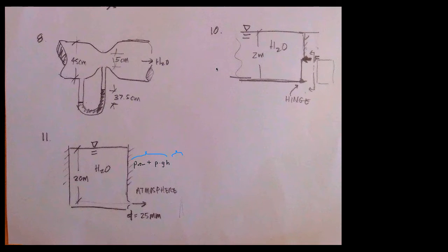But of course you know that this Venturi tube, the way it works is in a steady state condition of flow, the velocity times the area of this section must equal the velocity times the area of this section. So this has a faster velocity. And you know that the higher dynamic velocity means the hydrostatic pressure will drop in this area compared to this one here. So we're going to use our Bernoulli equation to solve this.